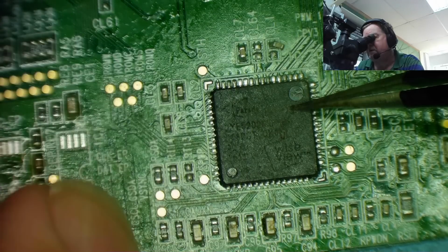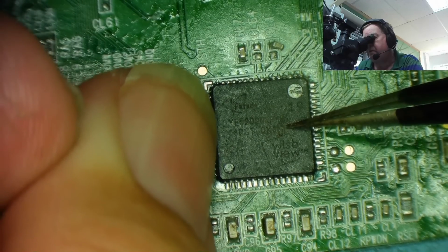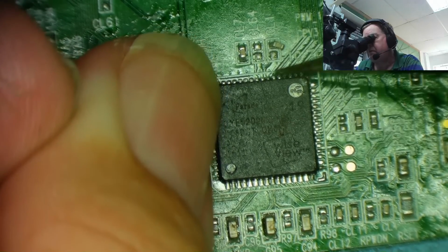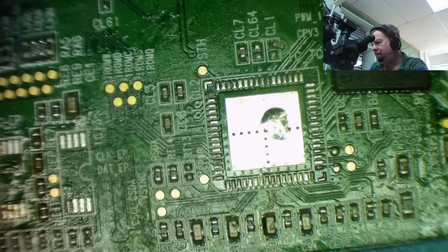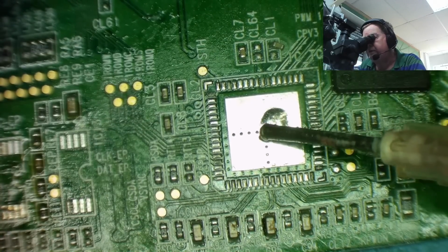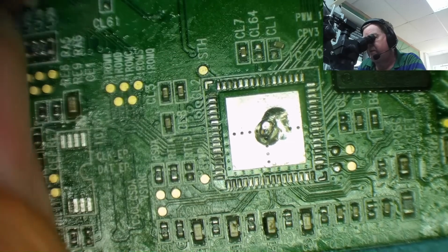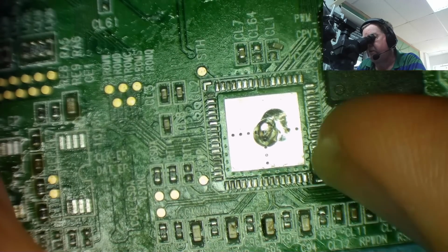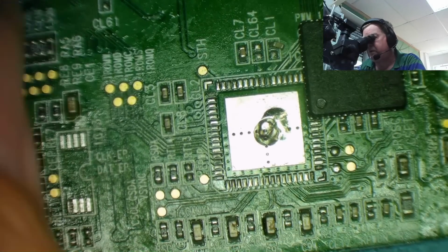I think what I'll do is tack down one corner once I'm happy with it being in place. No, you see, it's too far out that way now. Probably a bit of sticky flux under this is going to help actually. Let's get a bit of flux under it, because the flux is sticky, and that'll probably help to hold it in place while we get it positioned, and it shouldn't move. I mean, the whole board's sticky anyway from flux, to be honest.